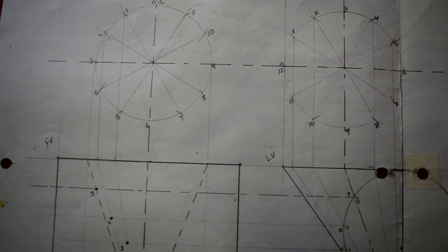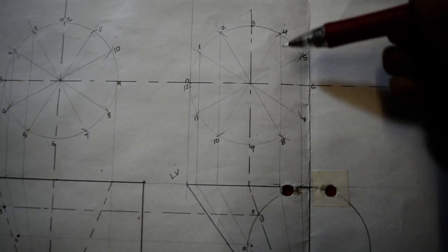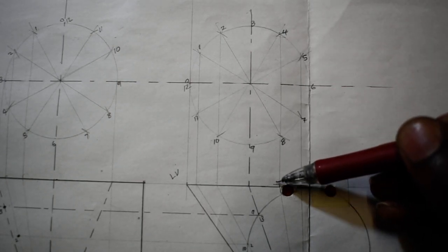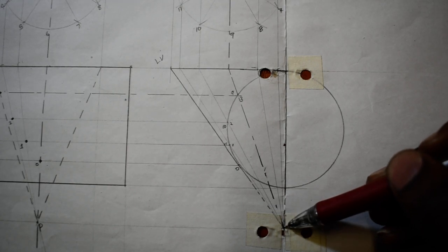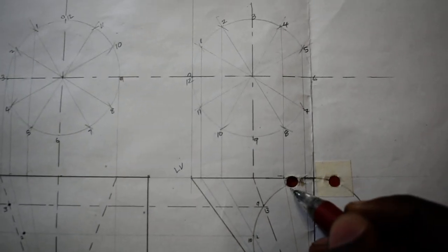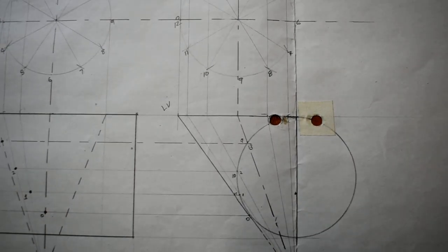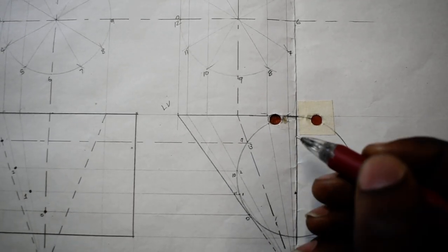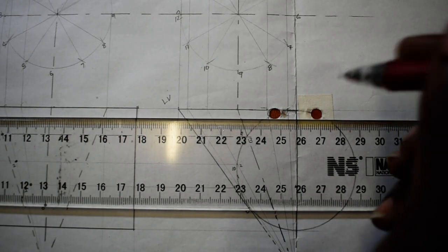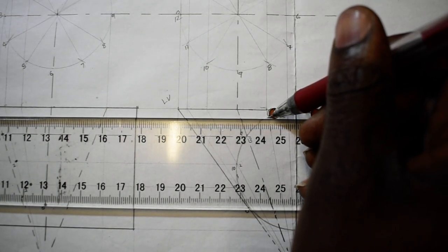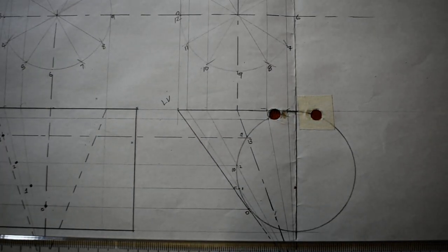A1. So get point 4. Go back to your auxiliary left view. Point 4 is that one. Trace it, there it goes. From there it goes to your apex point, isn't it? So once it touches the main pipe, which is touching right there, you understand? Sorry about the hole there, so I'm going to construct it. There you go, faint towards my front view.